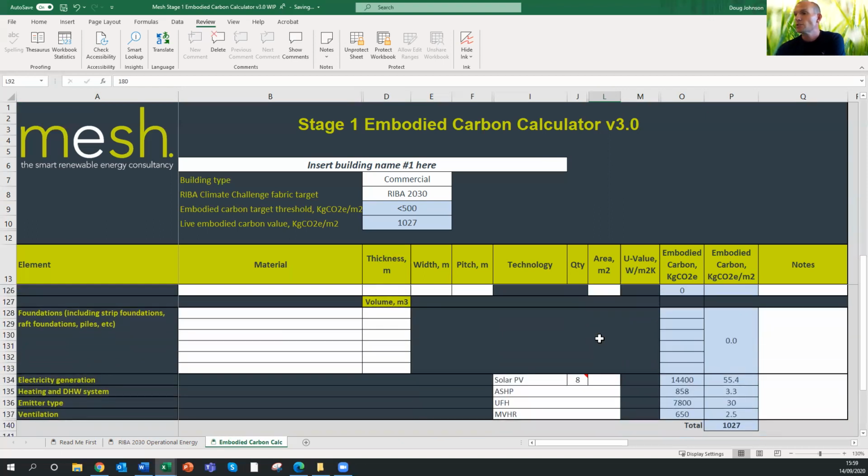And then just to wrap up here, we have now got 1 or 2 other choices for heating technology. So we've got air source, ground source, gas. We've also dropped in CHP there for more commercial dwellings, or buildings, should I say. We've still got underfloor heating and radiators, and mechanical ventilation are your options. So we've got a couple of extra choices on the heating.